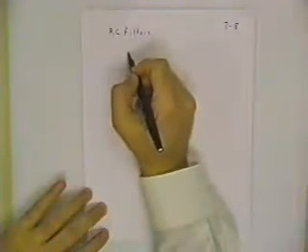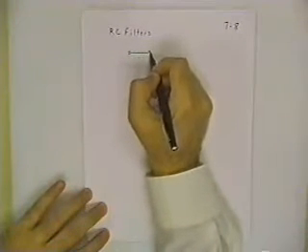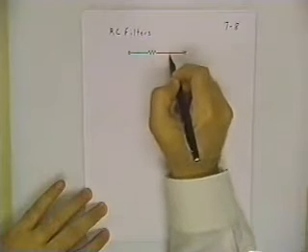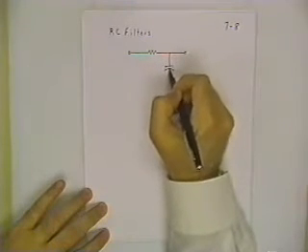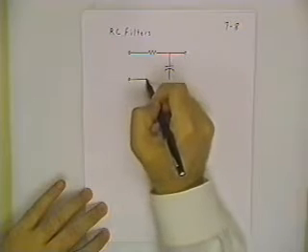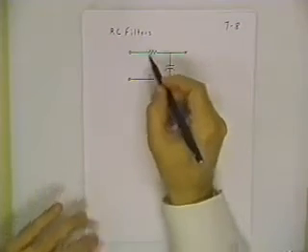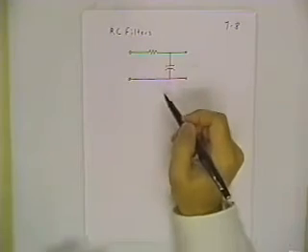All we need to understand these circuits is the basic impedance picture and Ohm's law in its AC form. And in fact, what I'm going to use is the voltage divider that I introduced earlier with DC circuits, but now I'm going to show you the voltage divider in an AC context, and that'll help us derive the behavior of this filter. This is called a first order filter because if you went back to solve it as a transient problem, it would have a first order transient response.